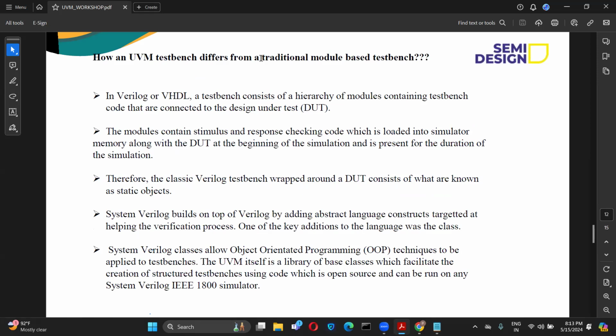The major difference between Verilog test bench and UVM test bench is the class-based stimulus that we give. Verilog doesn't support object-oriented programming, but SystemVerilog and UVM have this feature. The main purpose is reusability and the ability to cover as many features as we can of the DUT. From Verilog, we can just directly provide the stimulus, but that will be very hectic for a complex design.